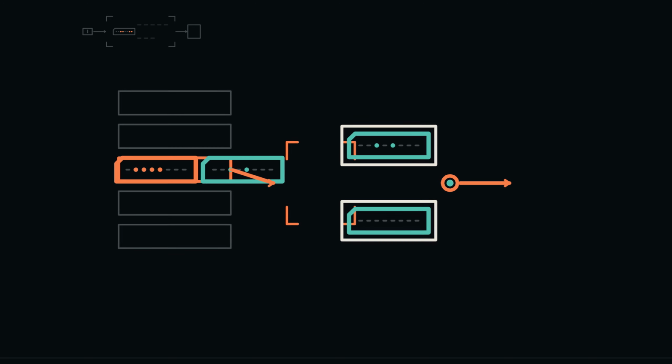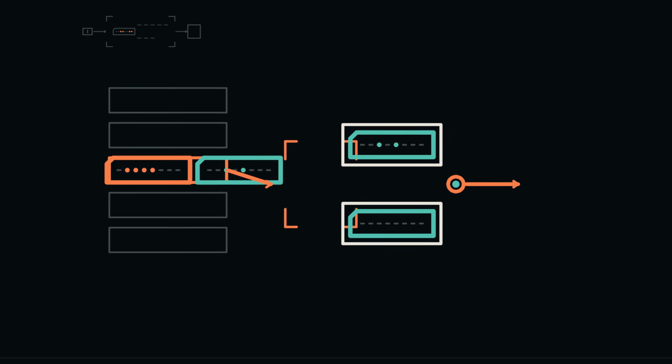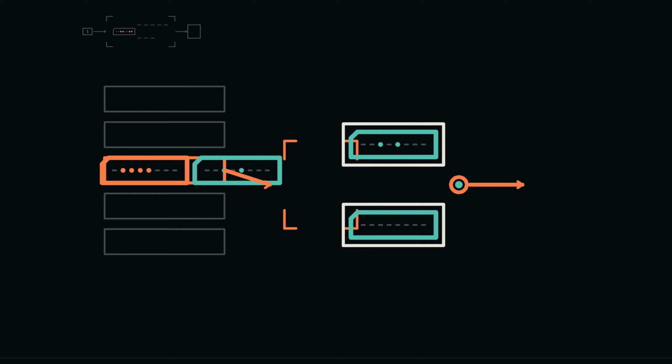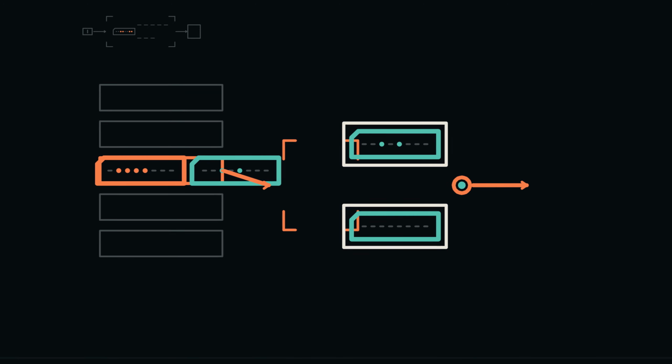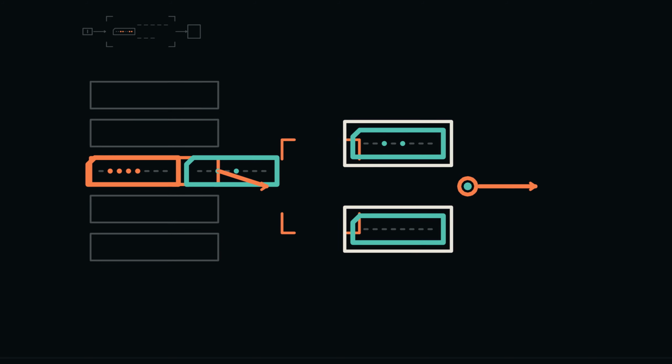1 minus 1 produces 0 in R0 and sets the 0 flag. Compare 0 with 0 leaves R0 unchanged and keeps the 0 flag set. The branch condition is now true, so the target address labeled done replaces the ordinary next address.